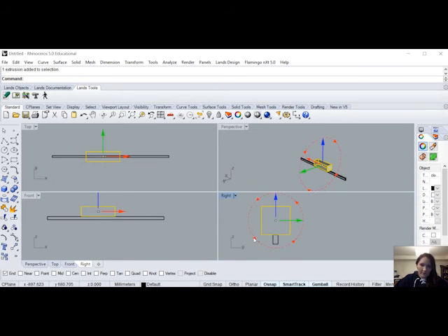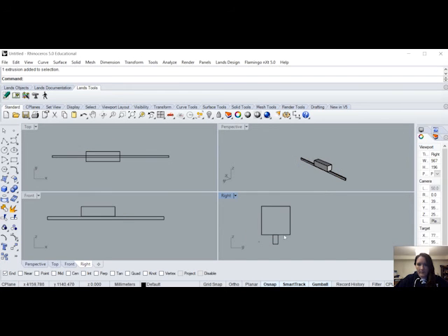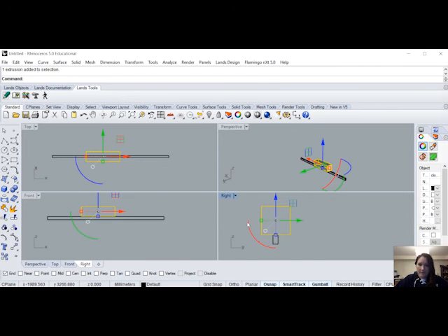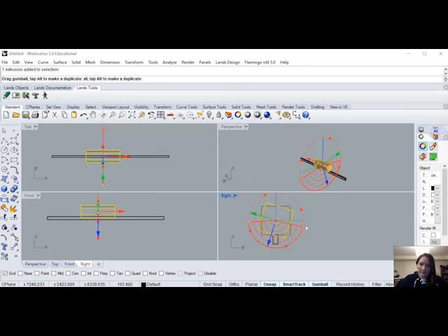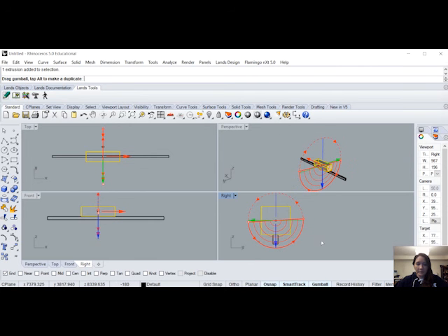So what you're going to do with this one is if you click on it, it's going to tell you an amount. I'm not going to do that. You can just hold it and you can spin it. And that lets you rotate. If you want to rotate and keep it sticking on its grid, so that way it's not these weird angles, press the Shift key and it will lock as it turns. So you can see it turning.